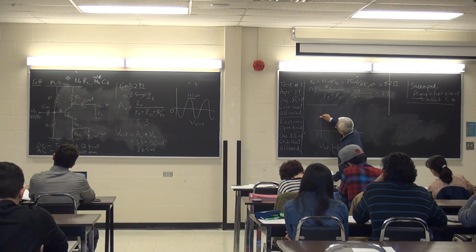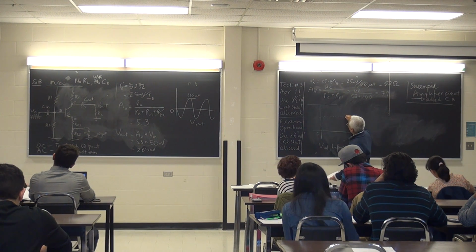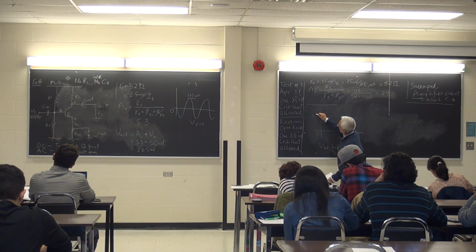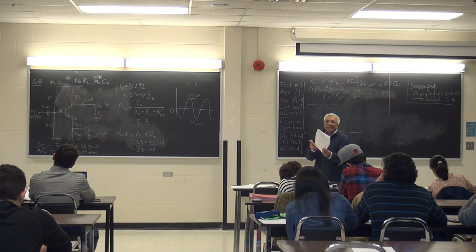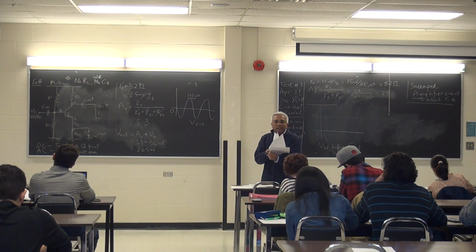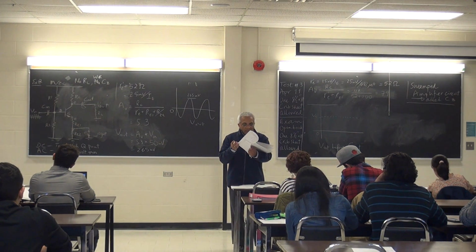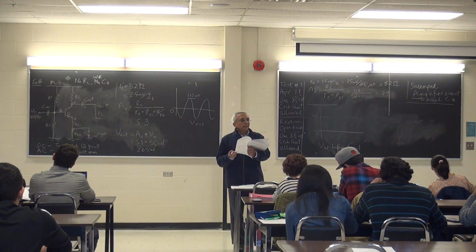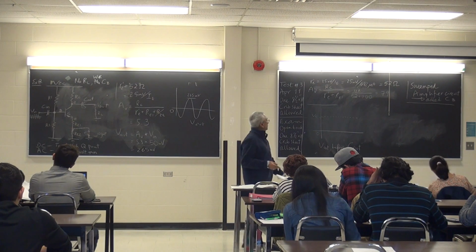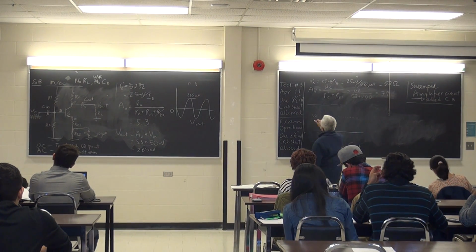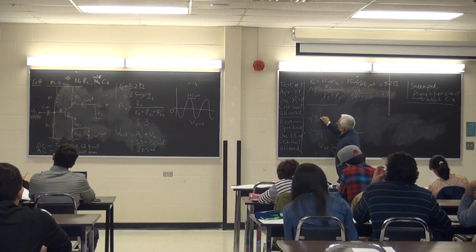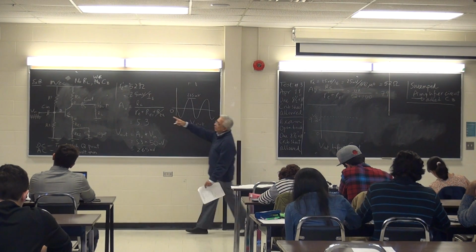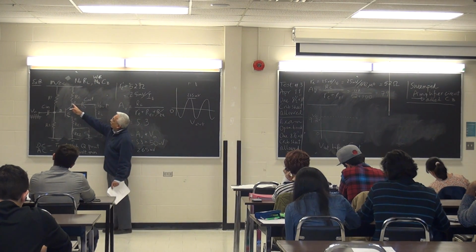So I'm going to show it right here with the dotted lines. And I'm going to put a VC there. And VC is a value I calculated for my DC analysis, and it's on page 8. How much was VC? Fourth calculation down. 9.2 volts. So if I was to measure a DC value here, it's 9.2 volts.